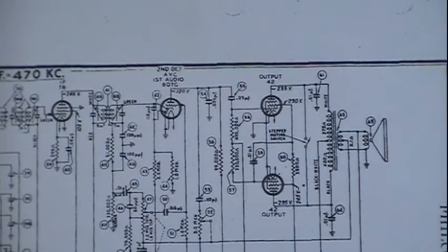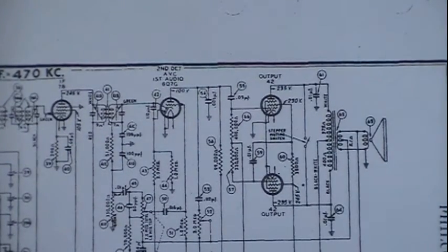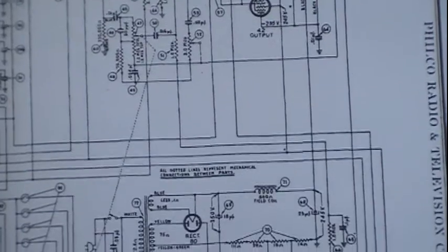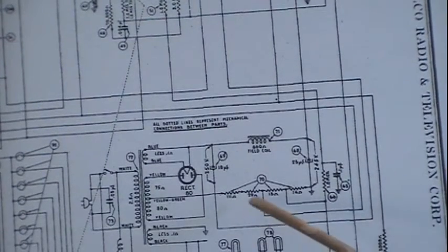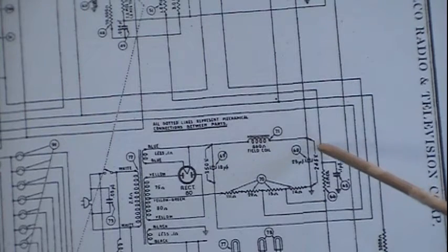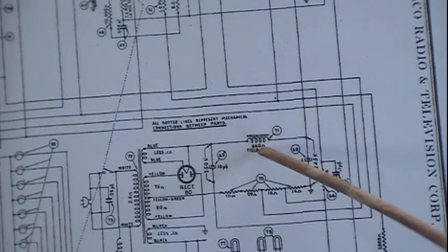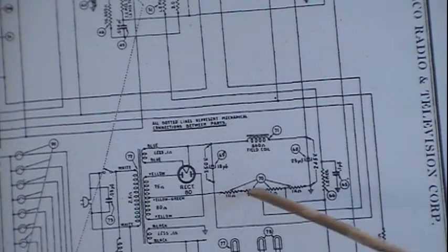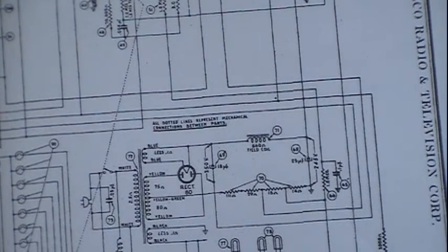But these two, I did a little bit of math on their biasing, which comes from the power supply here, right down in here. They're pulling bias off this line right here, so they had a voltage and resistance here, so I could actually figure out how much current goes through here, and that's the same amount of current that's pulling through these back to here through these resistors. And it works out that these are running about, I think it's minus 20 or minus 24, something like that. But in any case, it throws them outside the Class A range. It throws them in an AB range.